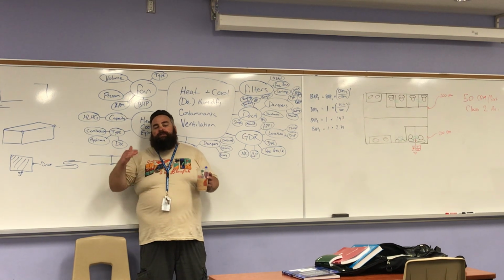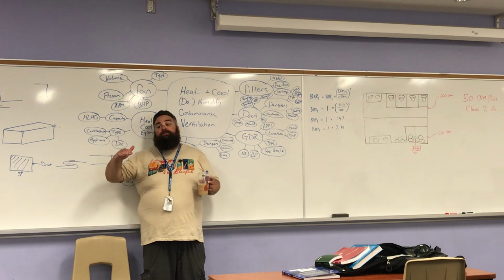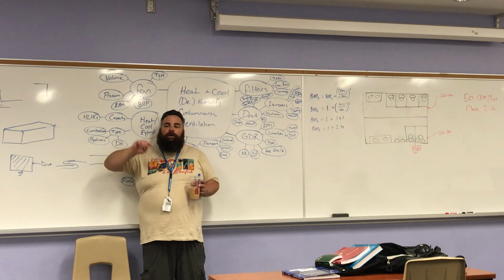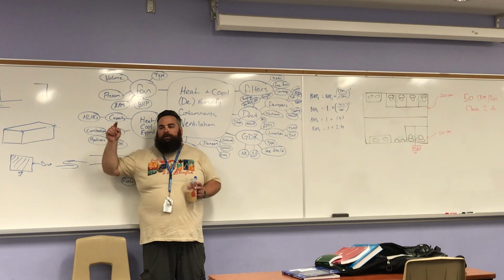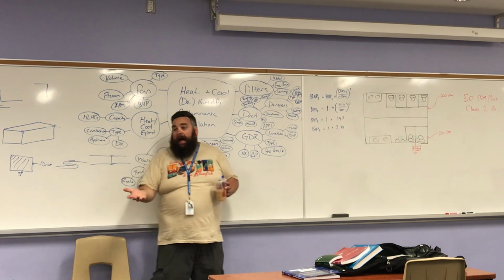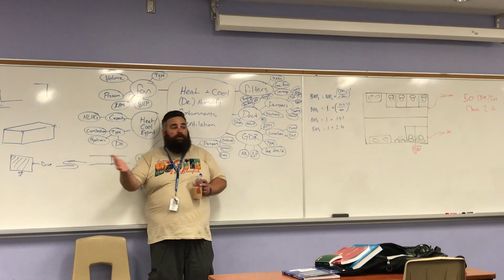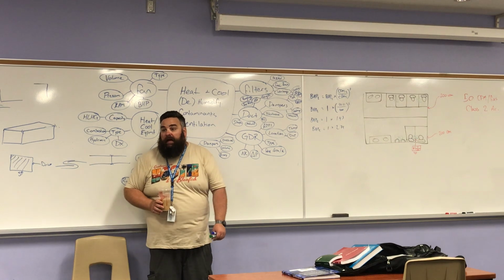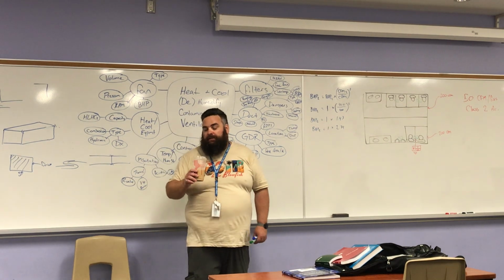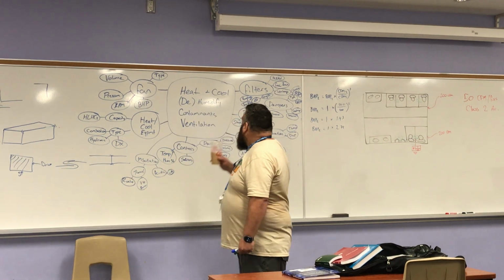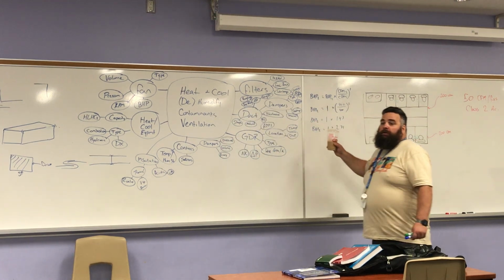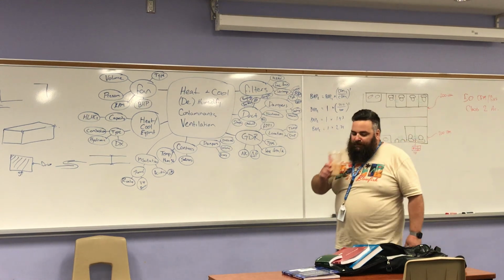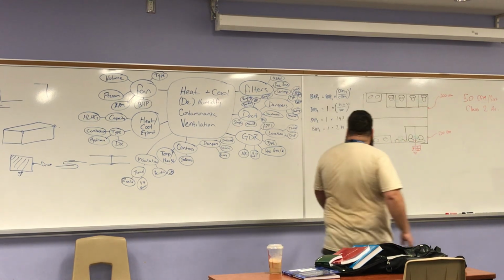So what we had was controls that would prevent these rooftops from coming up at the same time. Because the issue we had wasn't when they were running at steady state, it was the inrush current of the starting compressors. So these things happen, you can mitigate it with things like controls, or you also might have to upgrade the service, and that might disqualify a project because of the costs. So it happens. But that's why you have to know your fan laws, because you've gotta understand the impact of those changes. Okay? Awesome.